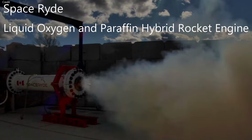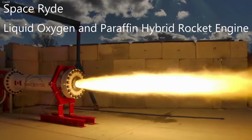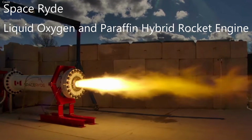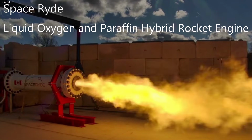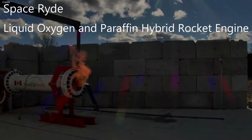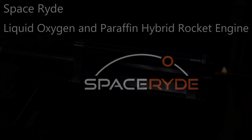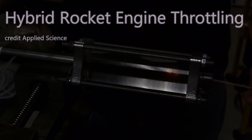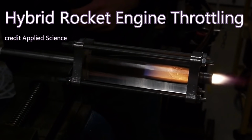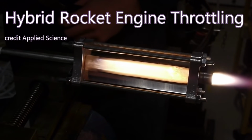Hybrid rockets use fuels like the HTPB we saw above, as well as paraffin wax and plastics, even nylon. But if these happen to be transparent, it's necessary to darken them with carbon soot or something else, so the light from combustion doesn't shine through and heat the rocket. We want all that nice heat going into combustion. Hybrid rockets are somewhat unique in that they have an ablative cooling system built into the combustion chamber. The heat of combustion is carried away in the vaporized products of combustion.